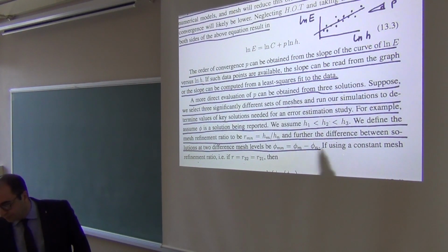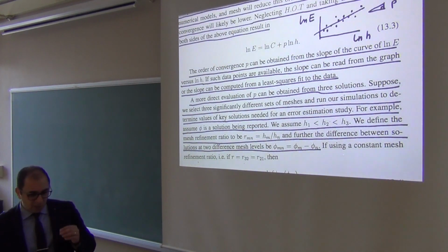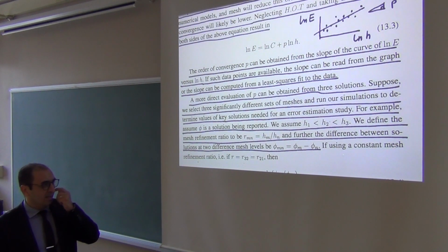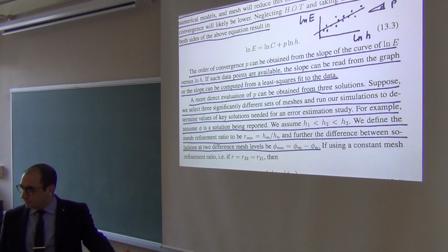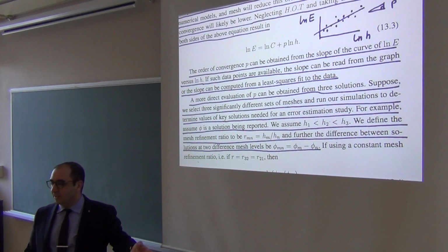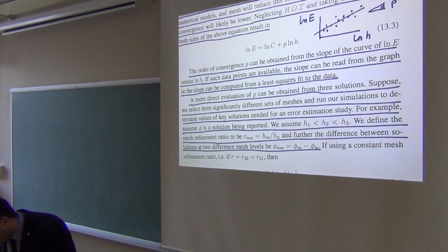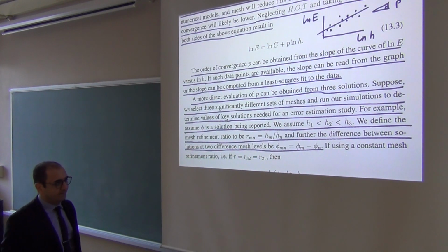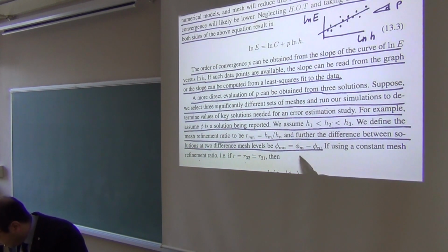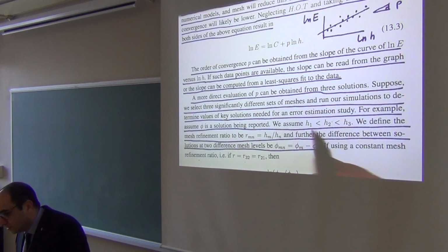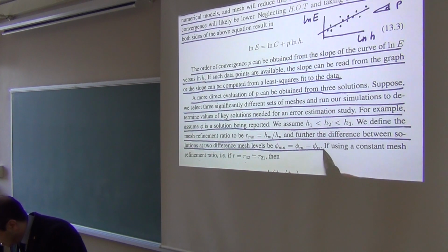Yeah, so it's the difference between the solutions you obtain. Let's say it's this nozzle that impacts paint on the surface. On one mesh it gives me 2 meters per second. On the next mesh, it gives me 2.2 meters per second. The difference between the solutions that I obtained was 0.2 meters per second. This I know as phi mn, or phi m minus phi n. I can do this calculation comparing mesh levels 2 and 3, or comparing mesh levels 1 and 2. It's up to me.